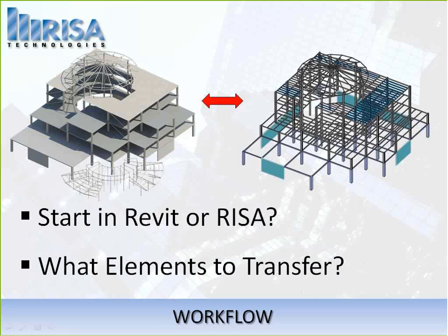So the big question always comes in, should I be starting in Revit or in RISA? And the answer to that is either. You can really go from either program into the other and back to the original one, which we call round tripping, with no difficulty, or at least very little difficulty depending on your experience level with the link.